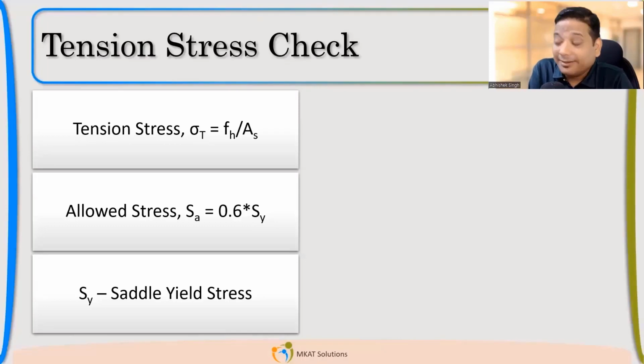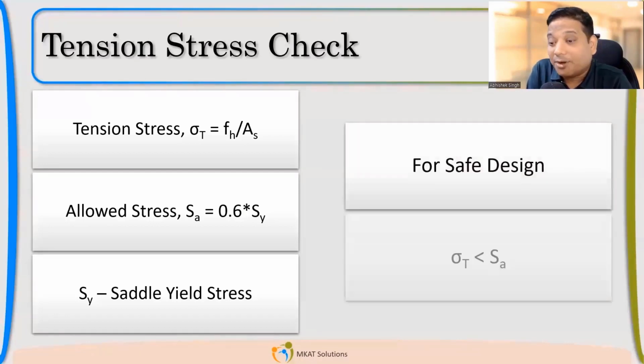But if it is given, then definitely you can take whatever temperature. But typically for saddle support, we always take room temperature. If it is insulated, then your temperature may be higher. Great. So one part is over, but the second part, bending, is not over.